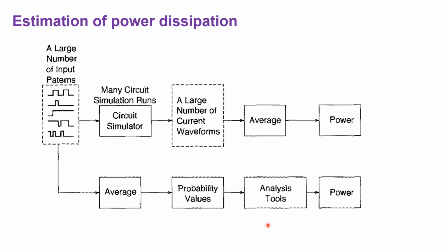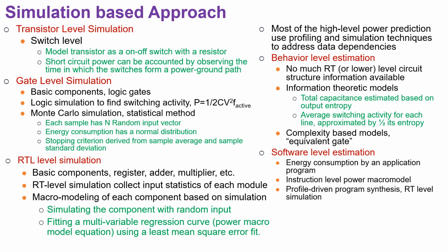Now using this, it is analyzed with a density simulator tool, DENSIM. Using the tool, the static probability, signal activity, transition density, and transition state probability are obtained. From this, the power can be estimated.